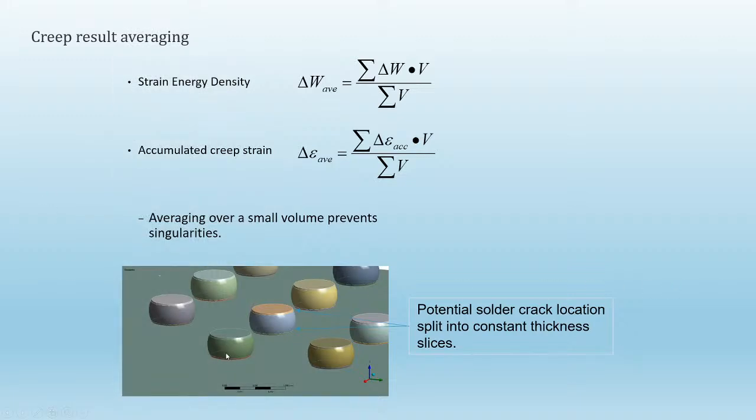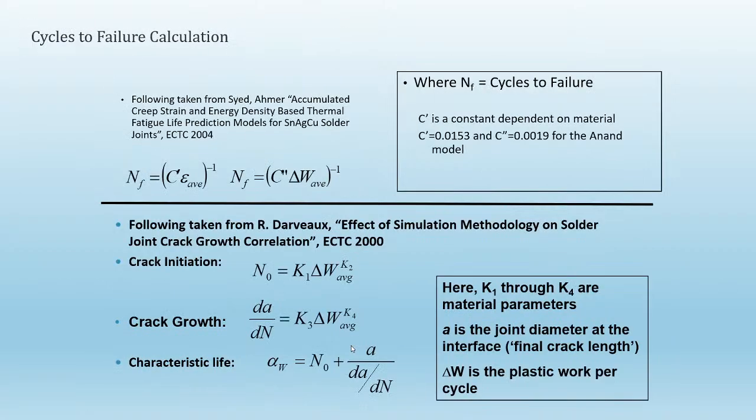And if you look at CPUs and BGAs, they're very different, right? They're not just typically surface mounted and leadless. Oftentimes there's heat sinks attached to them. There's clamping force to ensure enough pressure is applied to them. So the loading becomes very complicated, not necessarily just from thermal expansion coefficient mismatch. So that's another area that we want to focus on.